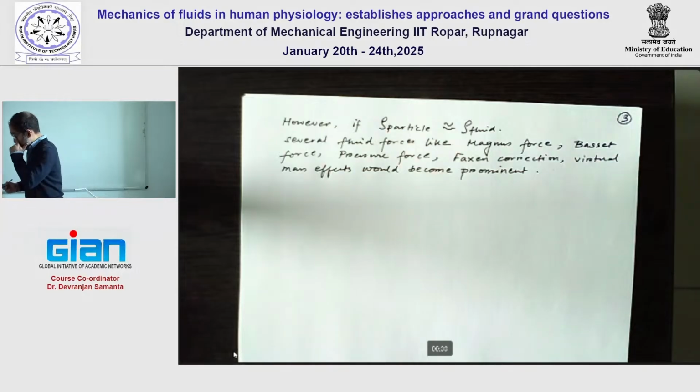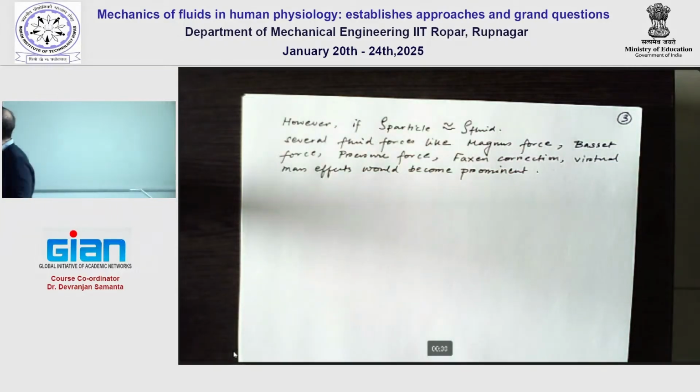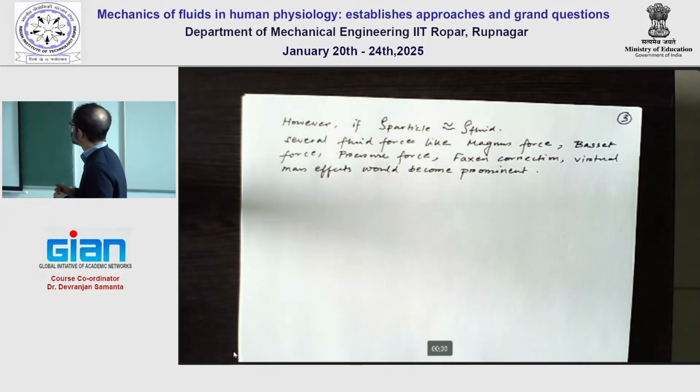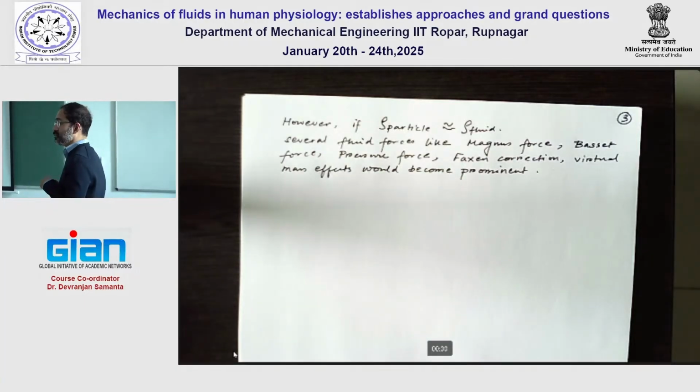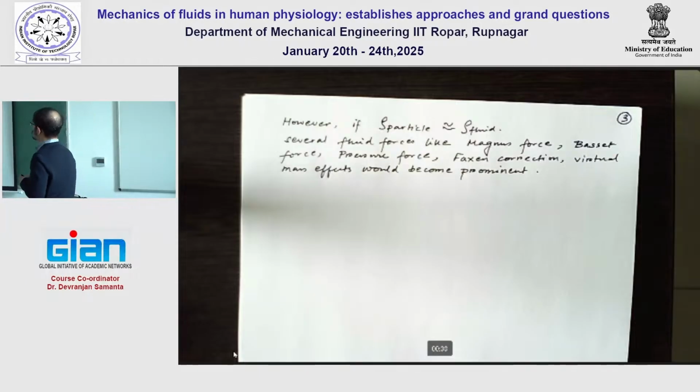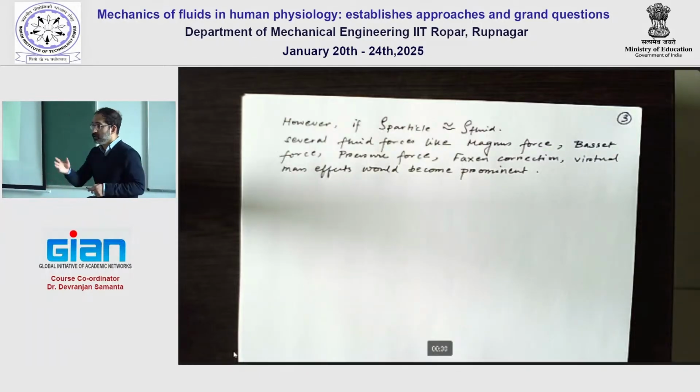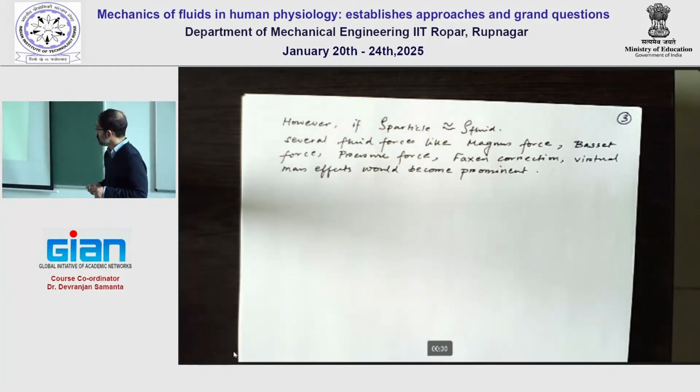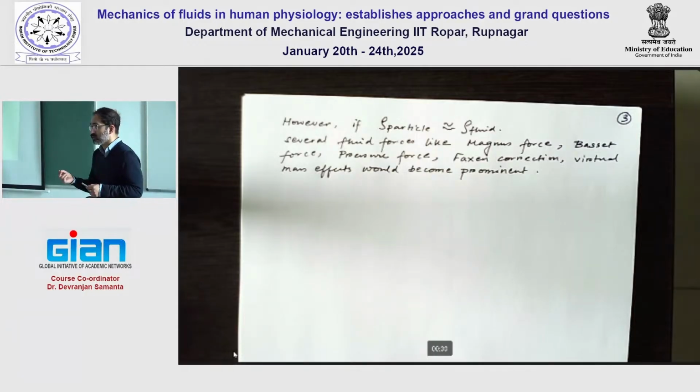Now, based on your problem that you're trying to solve, you might have to include some of these effects. In the simulations that we are going to run, along with the regular drag, and the gravity force is still there, it's a field force, I do include the Saffman lift force, because Saffman lift force is specific for particles that are very small and they act transverse to the direction of the particles.